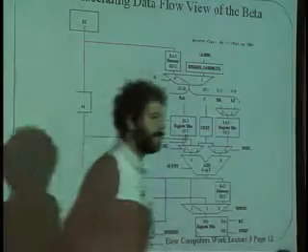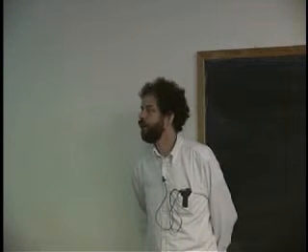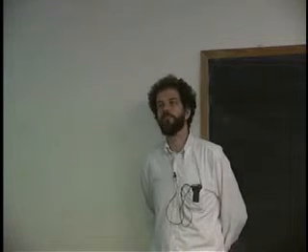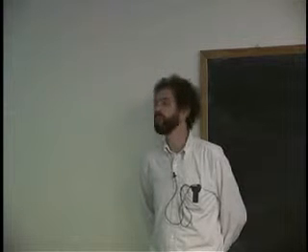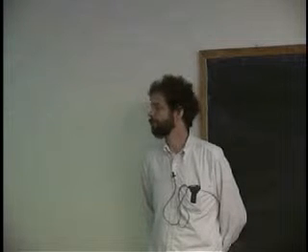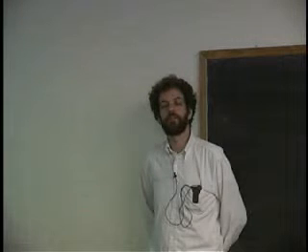Okay? Yeah? So if in our addition example, the data is ready to write and then gets written at the next clock cycle? That's absolutely right. At the end of every instruction, there is a clock that goes off. And that clock says, whatever the instruction was meant to do, let's now write the results. And writing the results means that we increment the PC and we write the results into the register file. And then we're ready to do the next opcode.